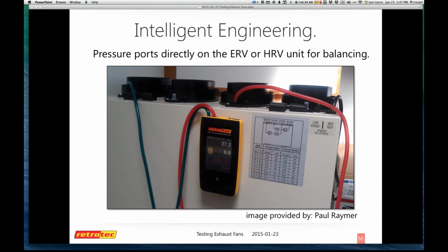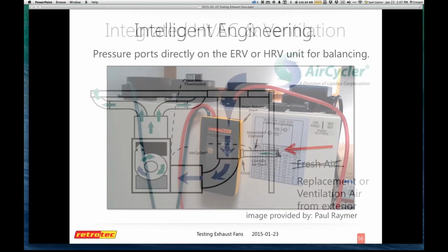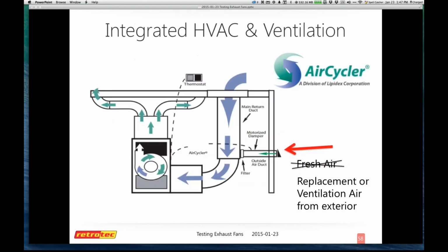One of the other ones that I frequently bring up is about how to measure the HVAC ventilation or the makeup air or additional air. I do not use the term fresh air because I don't know where it really comes from or what it's moving through to call it fresh. So replacement of ventilation air, that's a requirement in codes that actually have conditions where you do a blower door and you are equal to or below 5 air changes per hour, you must have an installed ventilation system.